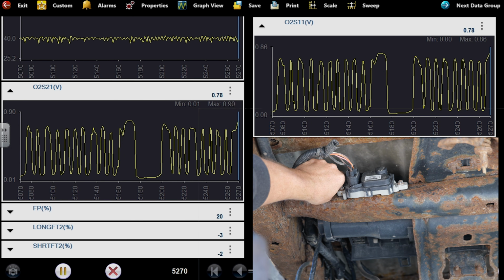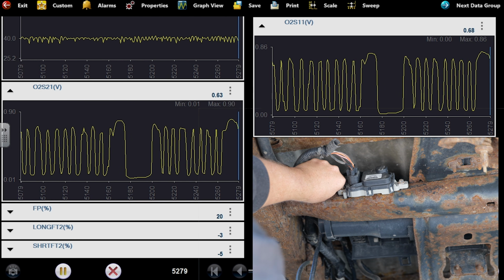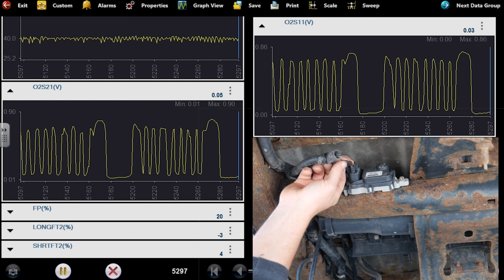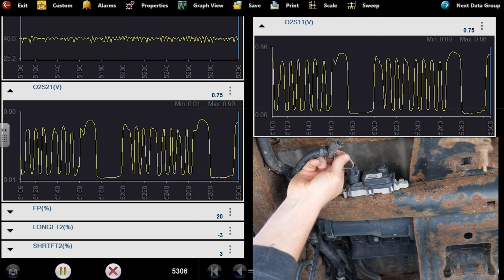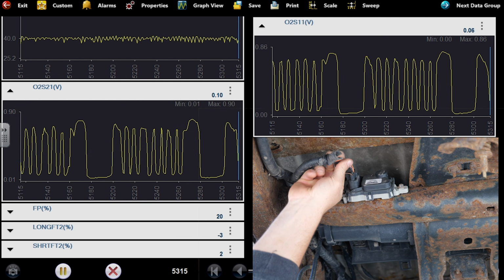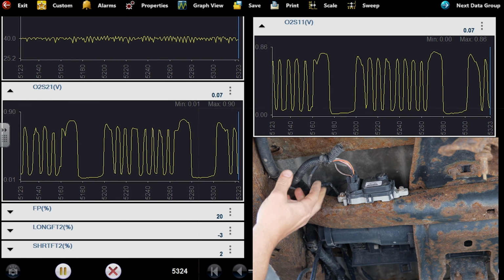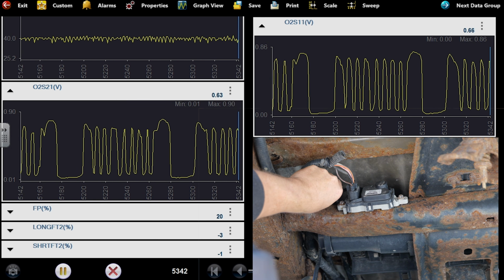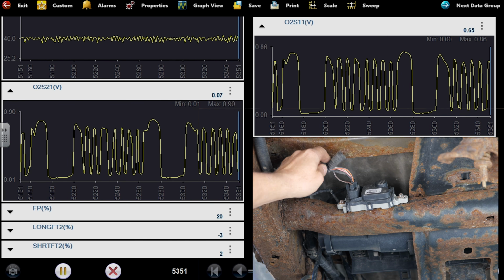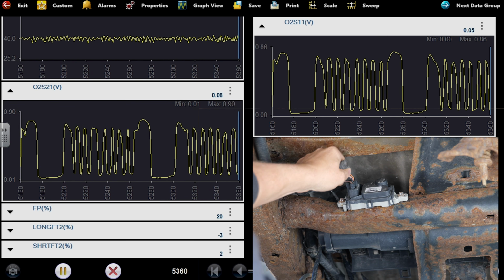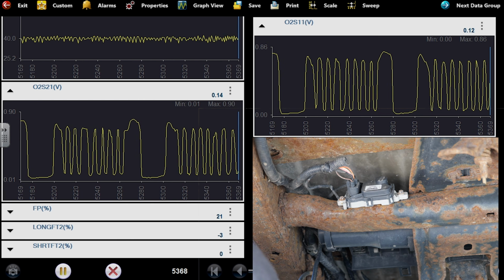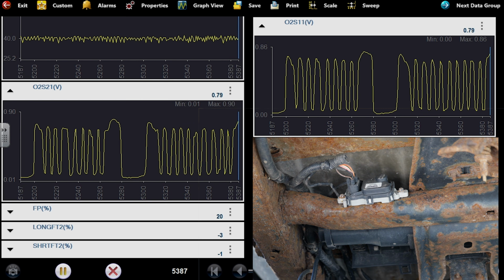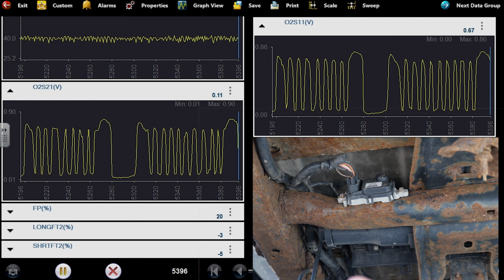I'm just kind of looking for fuel rail pressure to drop off, or my fuel pressure percentage to jump up, looking at the O2s to drop lean. If I start dropping fuel pressure, I'm gonna see that, and I don't have any of that going on. This ground is tight, and I'm wiggling it without any change. We could easily have a pump going bad. Damn it. Okay, I'm gonna get out of here.